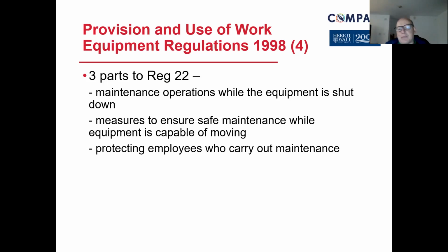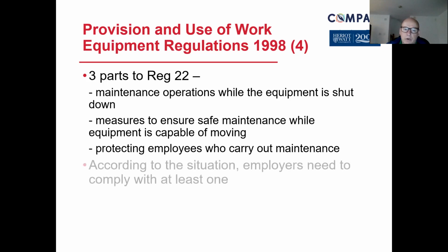So the classic example would be, rather than just issuing personal protective equipment for maintenance engineers, if they're doing electrical work, it may be you need a rubber mat so they've got extra insulation. It may be insulated tools so that the electric shock can't actually get to the hands, should we say, and so on. So thinking about the process to make sure that people who are doing the work can do it in a safe way without unnecessary exposure to the hazards.